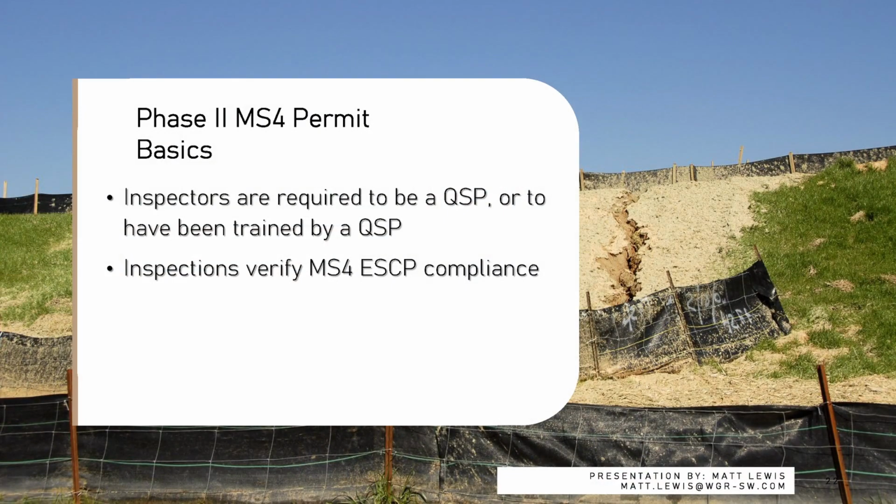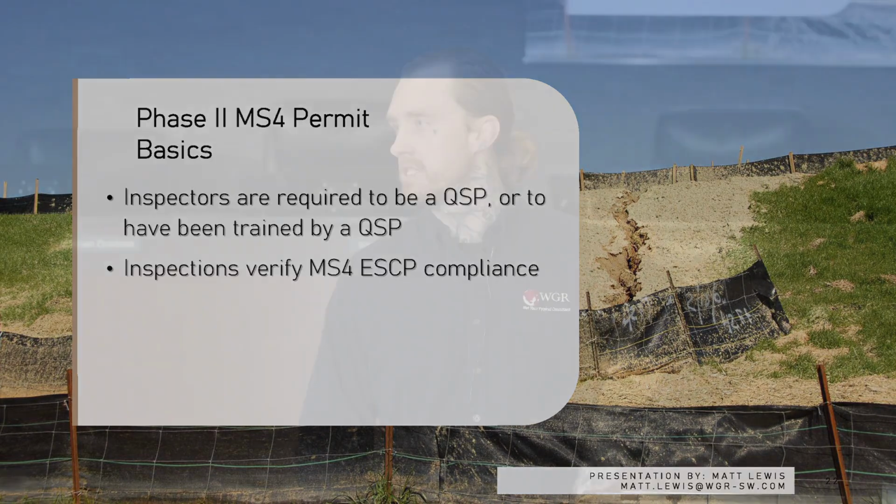So this is the typical ESCP compliance list. All right, so now we are getting into a little bit more of the BMPs. I guess I should mention this prior to submittal. ESCPs must be reviewed by a QSD or someone who is qualified and knowledgeable in the technical review of erosion and sediment control measures, or supervised by a QSD. PEs and CEs can technically self-certify that they're QSDs, but that might not guarantee that they have the expertise or the knowledge to properly review these things.